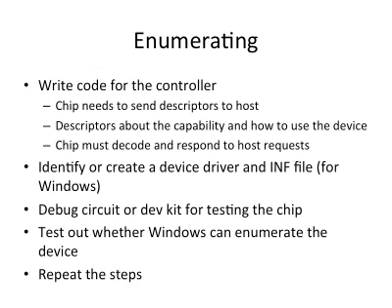Enumerating is basically you want to be able to present your device to the host as a known device. You will need to have firmware code on your device side for your controller, and this particular controller chip will send descriptors to the host following the USB communication protocol. Descriptors are in fact the information about the capability of your device and how to use your device. And chips must decode and respond to host requests.